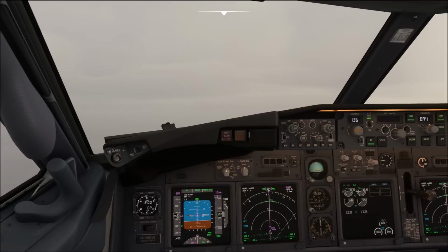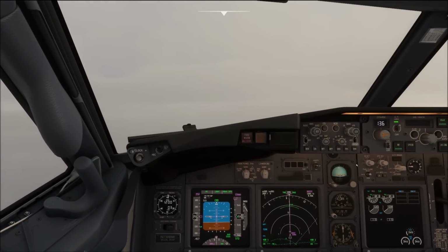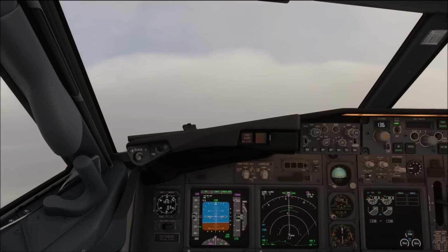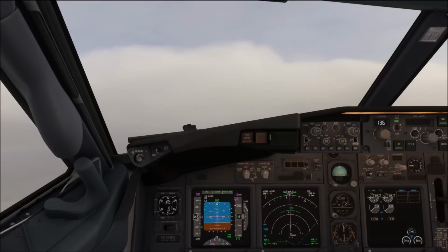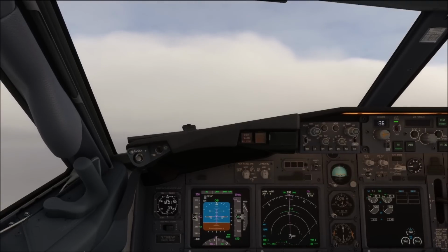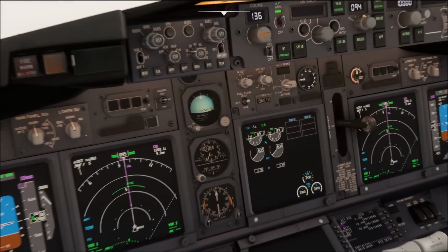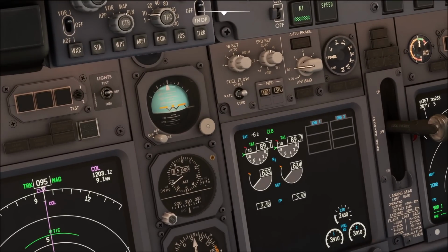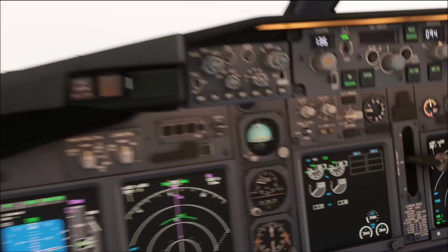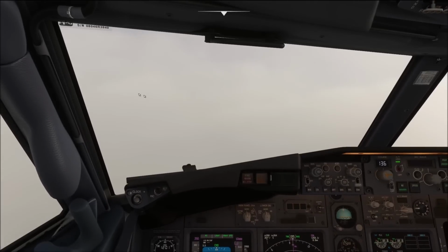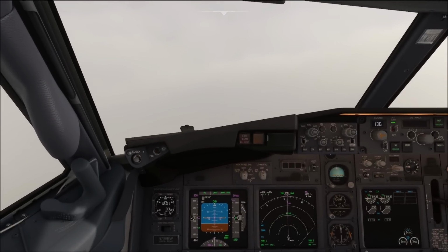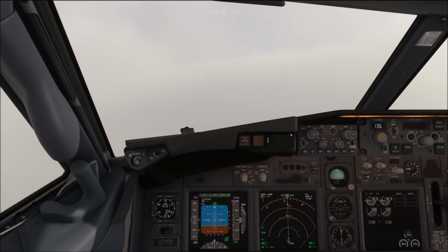And in flight, there is a rather easy rule in the climb and a rather easy rule in the descent as well. In the climb, you need to turn on the engine anti-ice whenever you are in temperatures of 10 degrees or less, showing on the TAT gauge up here, and there is visible moisture outside. Right now we are in clouds, those definitely count as visible moisture. So we have to use anti-ice.